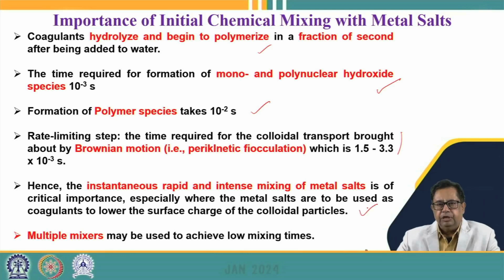If we require such a low mixing time, we may use multiple mixers so that the adsorption onto the surface of the colloidal particles can be brought about within a few seconds.